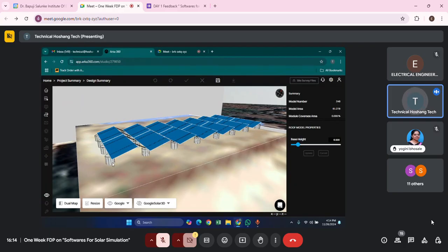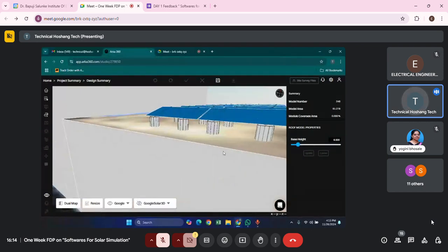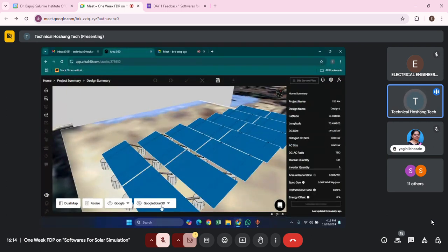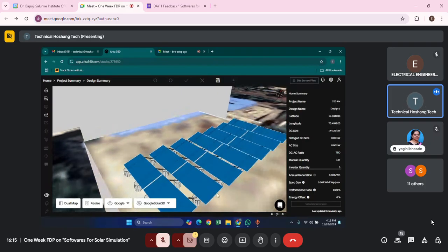Then you have to put an anchor bolt of almost 3 inches into the roof. Then you have to mix waterproofing cement in your concrete, and then make a proper mold having its legs properly aligned with all other legs, and then you have to fix the rafter and purlin. These 2 things.